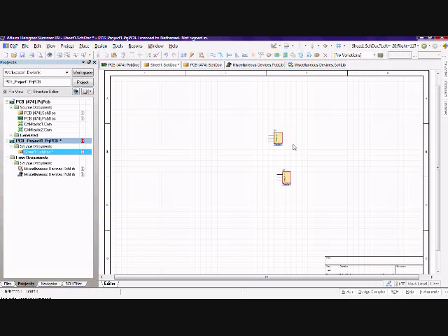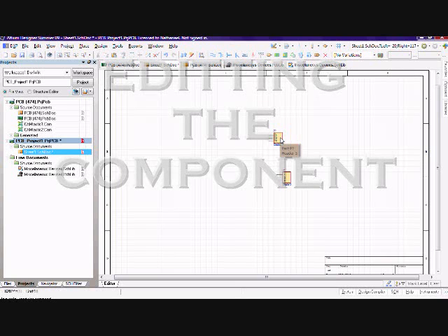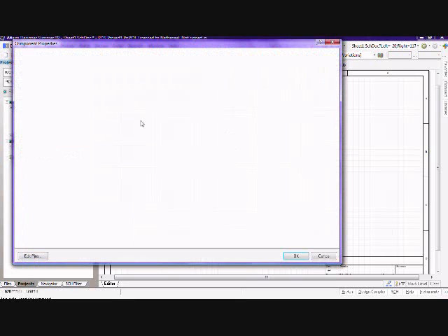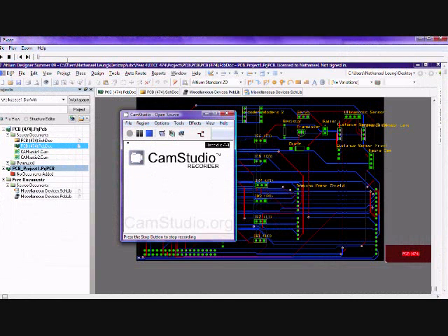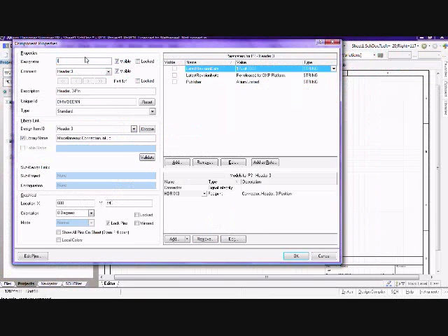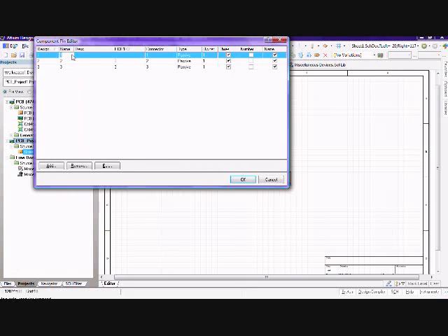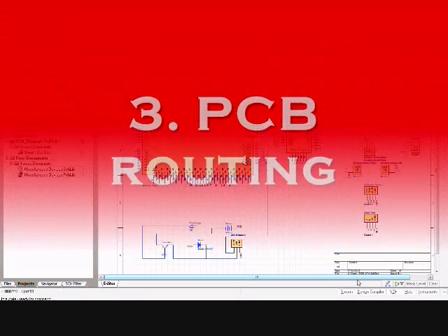Once you have the component placed onto the schematic, you have a choice of editing each of the components. So you click on this right over here, and the window will show up in terms of the properties. In the designator, we can rename the component to IR1, and also you have a choice of editing the pins over here, in which you can name them 5 volts, ground, and in. Once you have all the components connected and placed, here is the overall schematic diagram of our project.